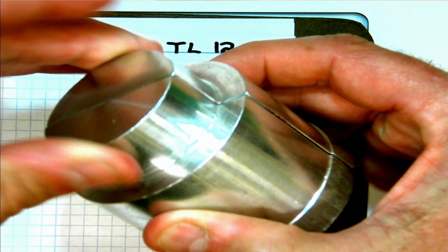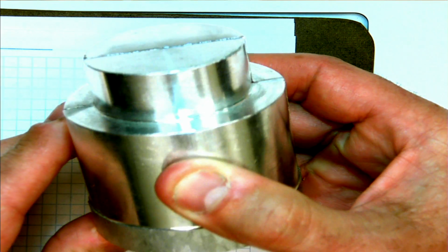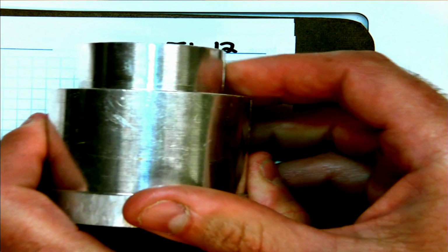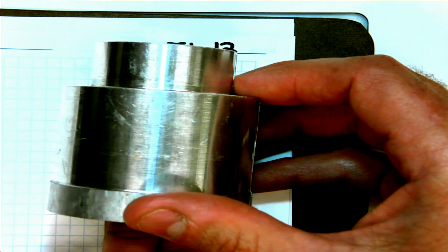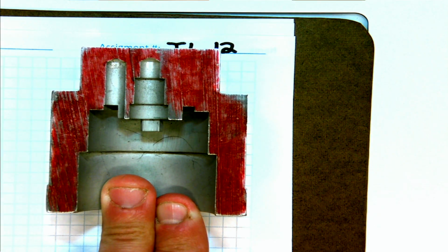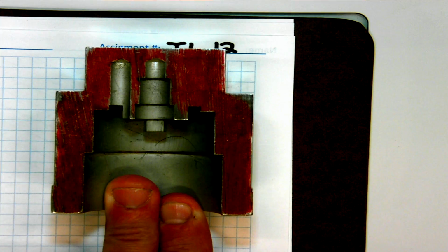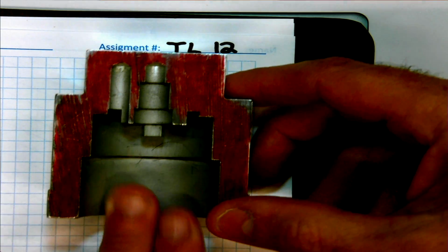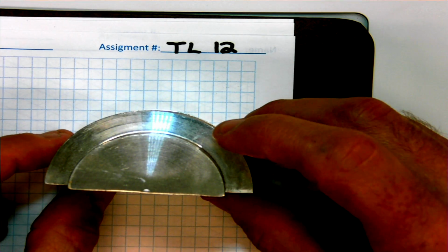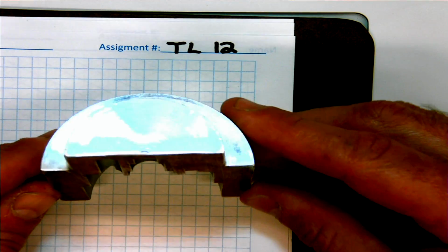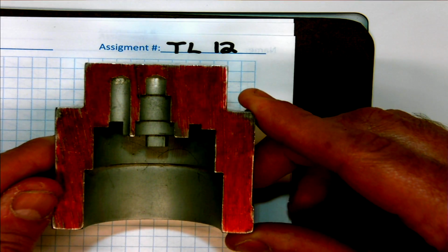Looking at it from the outside, we do see it's a symmetrical part. So what does a section view do? It takes this thing and it imaginarily cuts and removes part of the object to show interior detail of the object. Okay, so where this thing is cut, looking at it from the top, you can see it's a symmetrical part. Wherever this thing is cut, material-wise, that appears in red here.